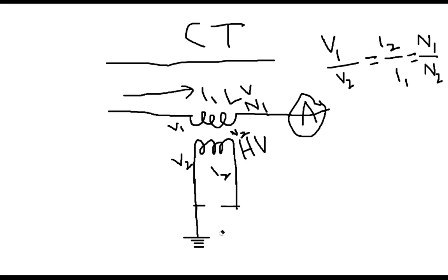So that's why it is recommended, if you need to take out the ammeter for some reason, that before doing that, first you have to make a switch. Therefore, typically there is a switch. It is called the shorting switch.